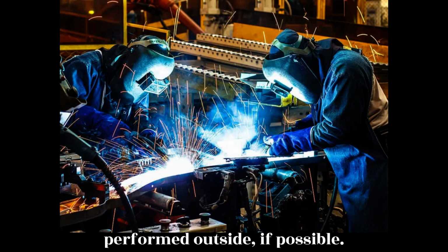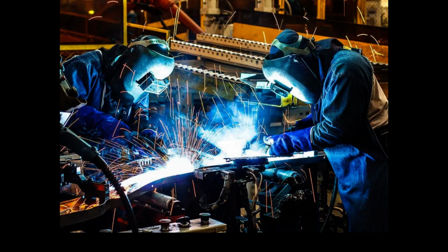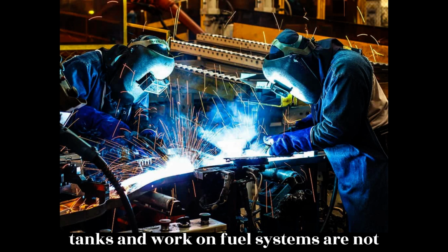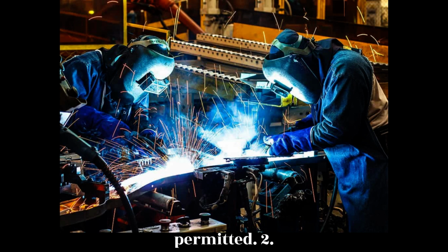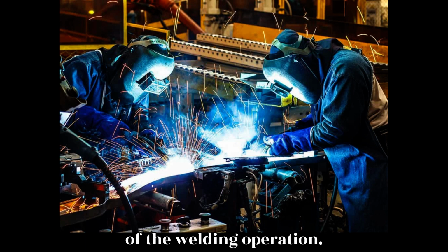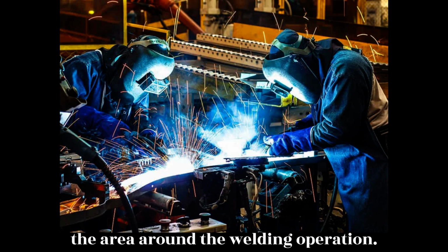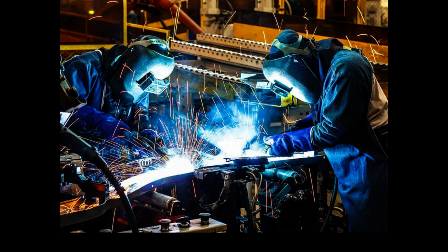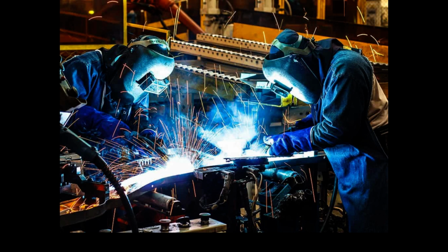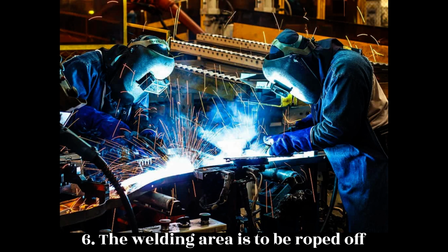Welding on an aircraft should be performed outside, if possible. If welding in the hangar is necessary, observe these precautions. 1. During welding operations, open fuel tanks and work on fuel systems are not permitted. 2. Painting is not permitted. 3. No aircraft are to be within 35 feet of the welding operation. 4. No flammable material is permitted in the area around the welding operation. 5. Only qualified welders are permitted to do the work. 6. The welding area is to be roped off and placarded.